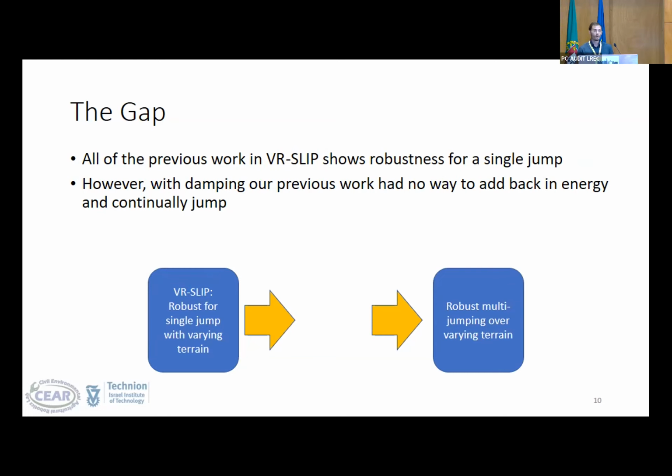For our optimization process, we also simplified things. Rather than trying to optimize the leg over many jumps over randomly generated rough terrain, we instead optimize over a single jump, changing only the initial conditions. For instance, here we're changing the terrain level while keeping the forward velocity constant, and on other runs we would change other variables. Through this, over multiple single jumps, we can come up with an optimal polynomial for the leg shape, the leg stiffness, the SLR, and the torque.